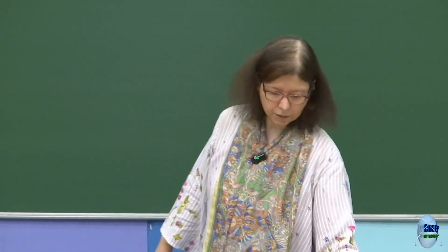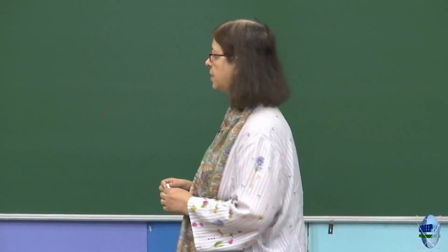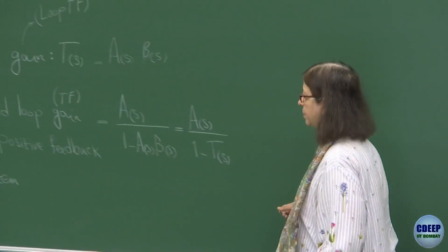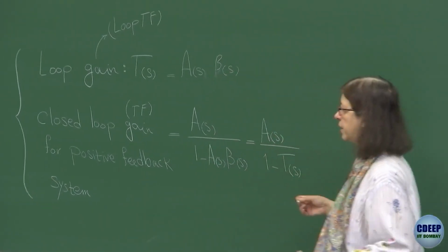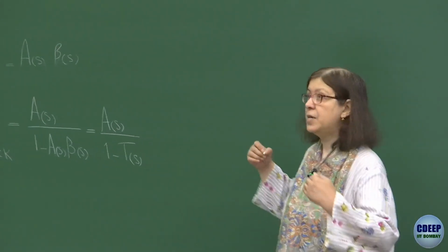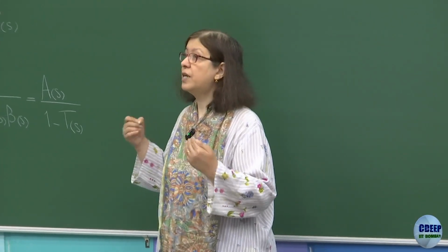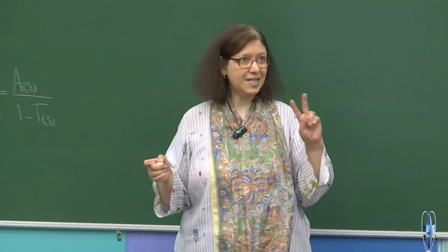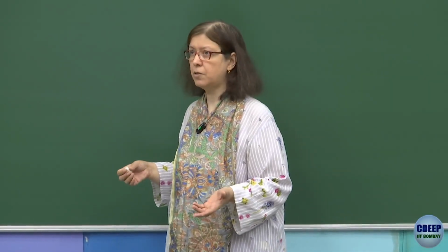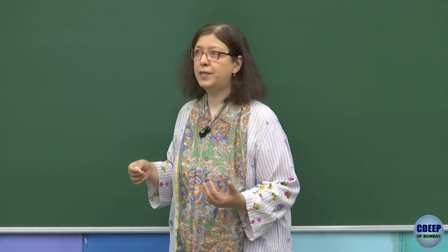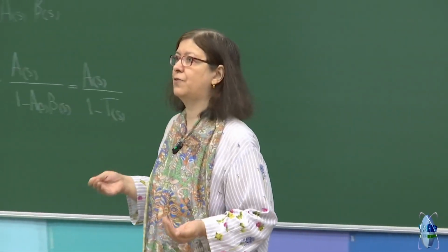And one thing also, just to conclude: when you apply an input to get a closed loop transfer function, be very careful that the input that you apply should not change the circuit. That was the second point we discussed last time. In the example we had, which was back-to-back transconductors, if you apply a voltage source, effectively when the voltage source is 0, you are shorting one of the nodes to ground.